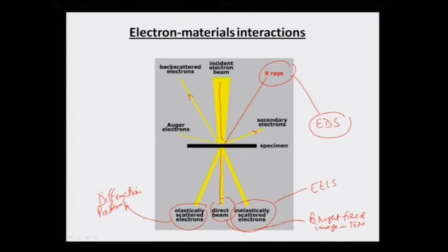What I have not talked about is that backscatter electrons can also be used to obtain crystallographic information in SEM. There is a new technique which has been developed of late, from the 1990s, known as electron backscatter diffraction or EBSD, that is used extensively now to get diffraction information as well as for texture studies in materials.